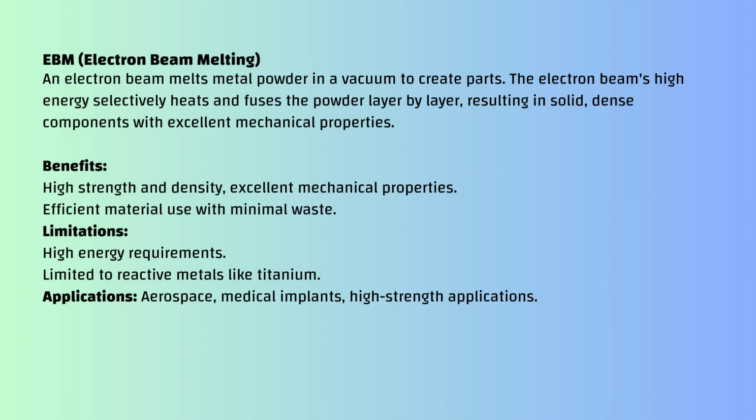EBM offers high build rates and produces parts with exceptional mechanical strength. However, it's limited to conductive materials, requires a vacuum environment, and typically results in rougher surface finishes compared to laser-based systems.